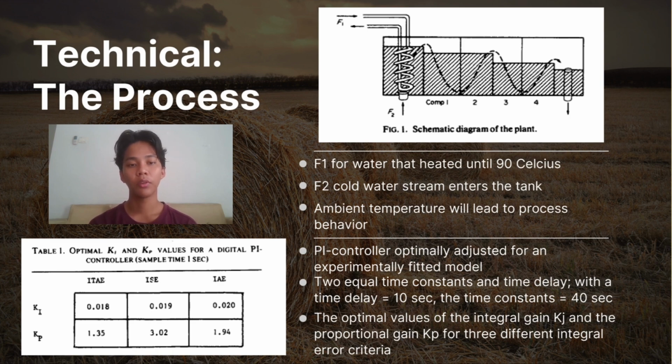One of the main difficulties of this controller was that it needed adjustment to operate over a wide range of desired temperatures. It is clear that a more sophisticated controller with a stochastic and adaptive model than just a PI type could have a better performance. Hence, the comparison between the PI controller and fuzzy control should be regarded as only a rough indication of relative performance.